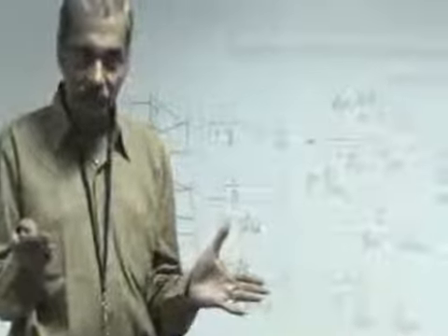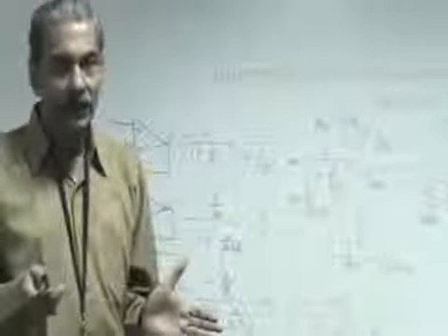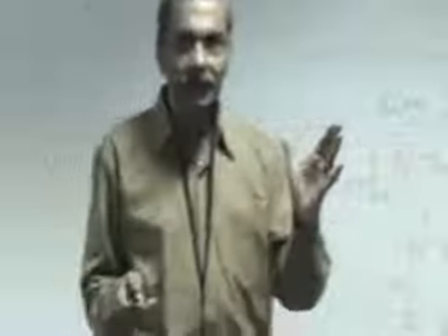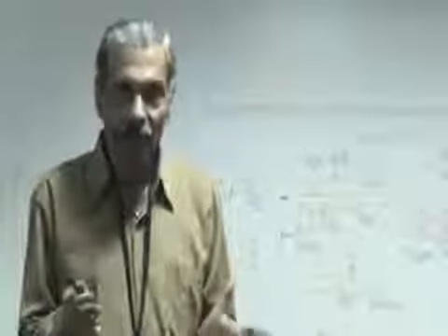Further, we have the time response to be understood. In time response, if you give a square wave to a unity gain amplifier, a square wave of the same amplitude is supposed to appear at the output. However, it gives us a rate of rise which is not abrupt but controlled by the maximum rate at which the output of the op-amp can rise, and that is called slew rate.